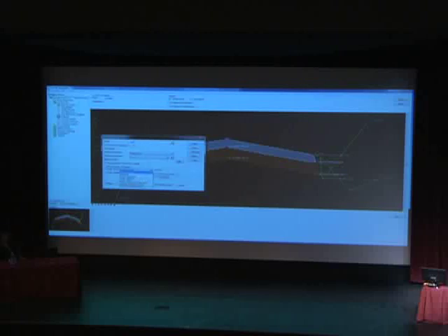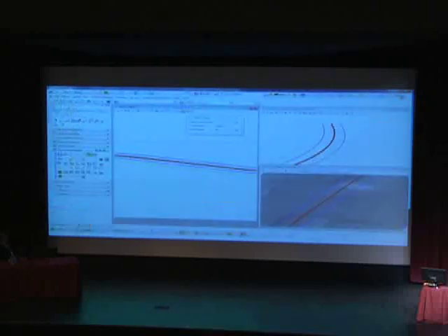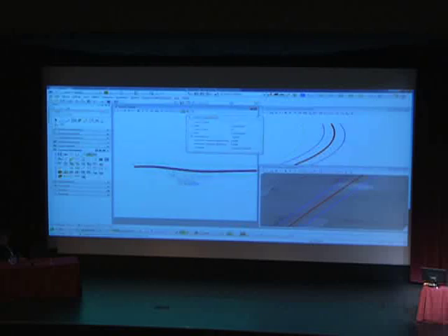Now what that is, that's an end condition, and an end condition could target a terrain model, it could target a feature definition, it could target elevation. In this case, it's just going to target a terrain model. And then on the right-hand side, I'm going to get it to target a feature definition of grade ditch bottom, right? Because that's what we want to tie into. So next I'm going to drop my template across the whole corridor, just like you're running your hinge criteria file across the whole project, just to check everything out.